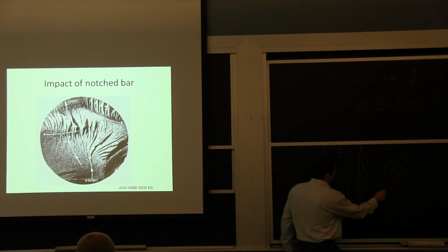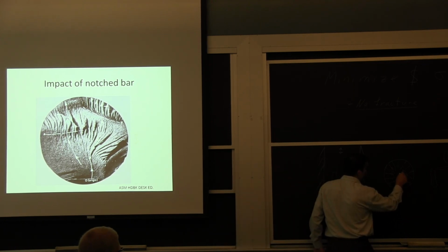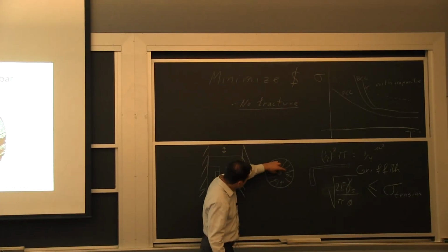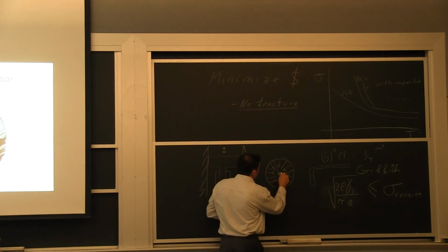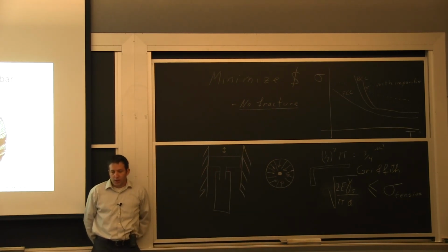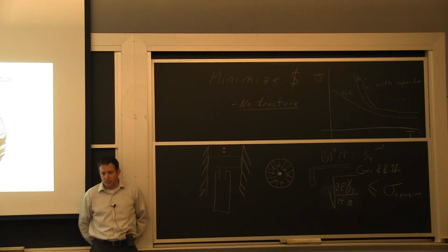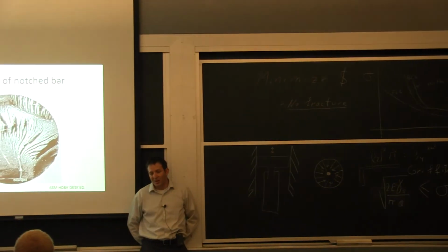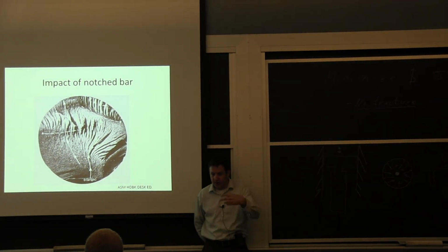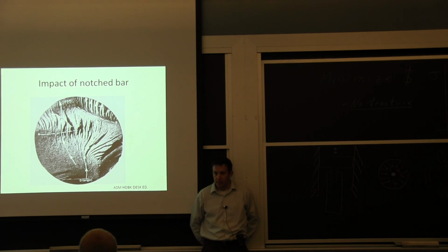So when all the cracks got close together near the middle, there's this one zone left, and at one point in time, this is the amount of material that was still connecting, right here, and you can see the crack arrest line around it. It's a little button. So it may look like little details, but they make a big difference when it comes to looking at the surface and making some basic interpretation. These are the only two types of line that you really have to worry about just by looking visually.